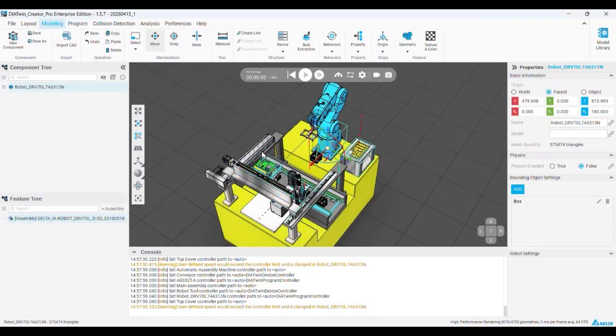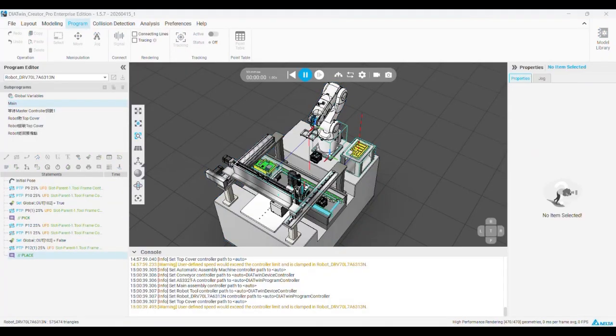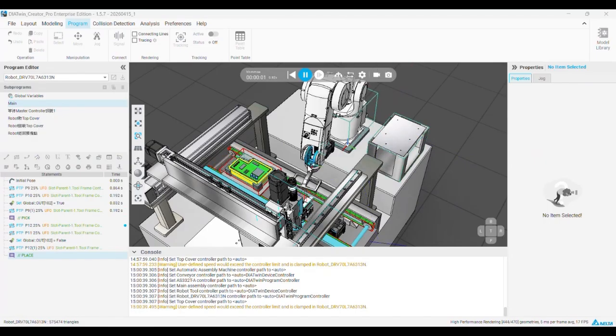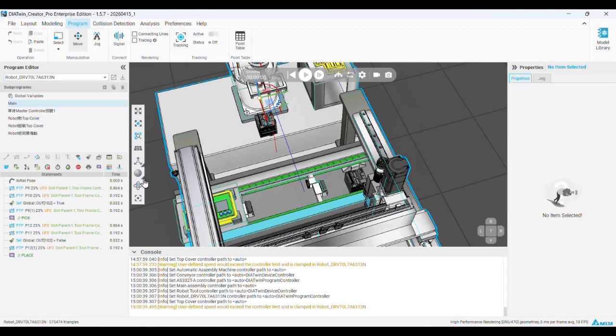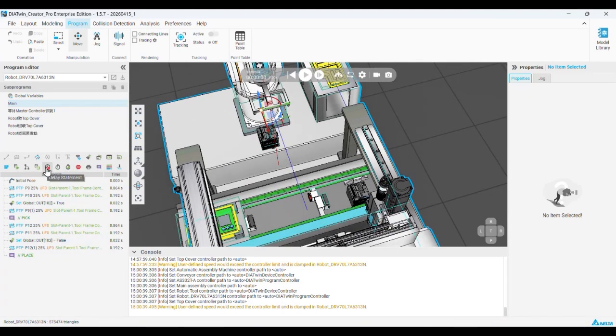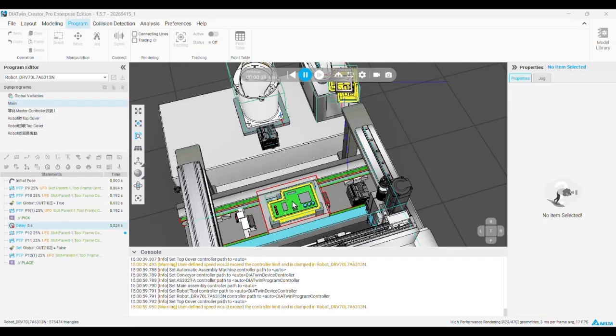So now, when we start simulation again, this is place. When we start simulation, we can take a try. Pick. You can see it released too fast, right? In yesterday's training, we also did a handshaking signal with each other. But I think right now we can skip this, because today's modeling training, we can just make some delay. So maybe pick, and wait for 5 seconds to make sure the product has arrived at this position.